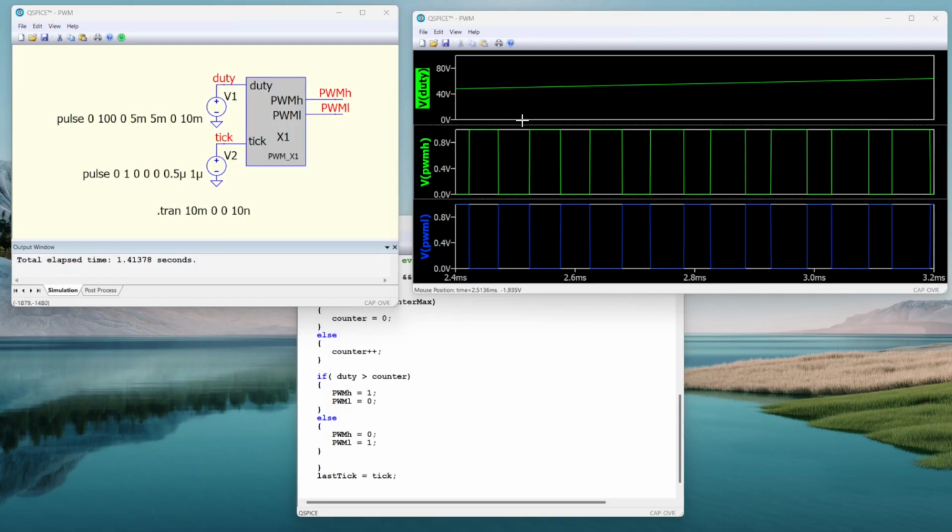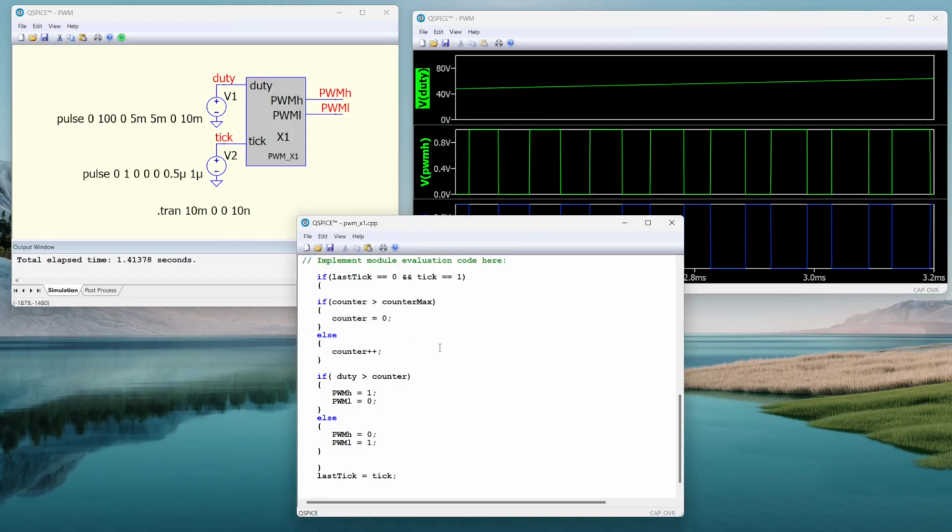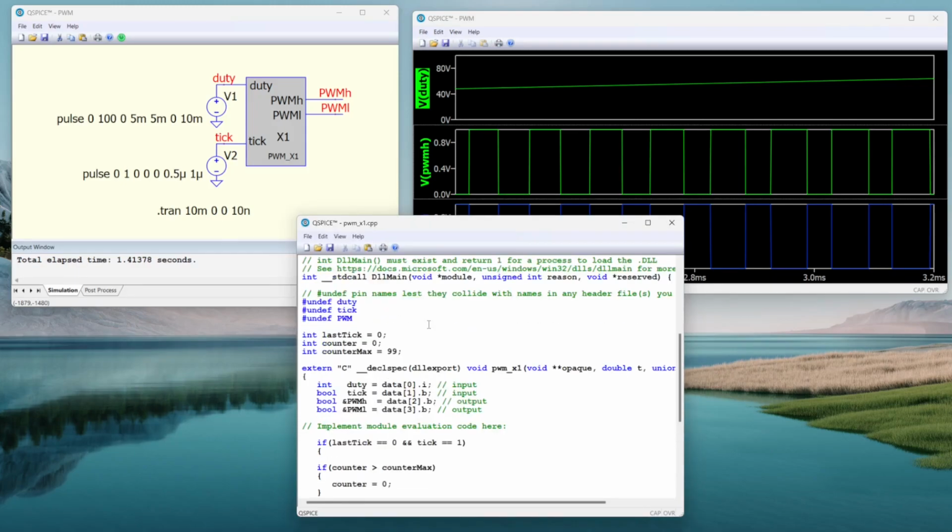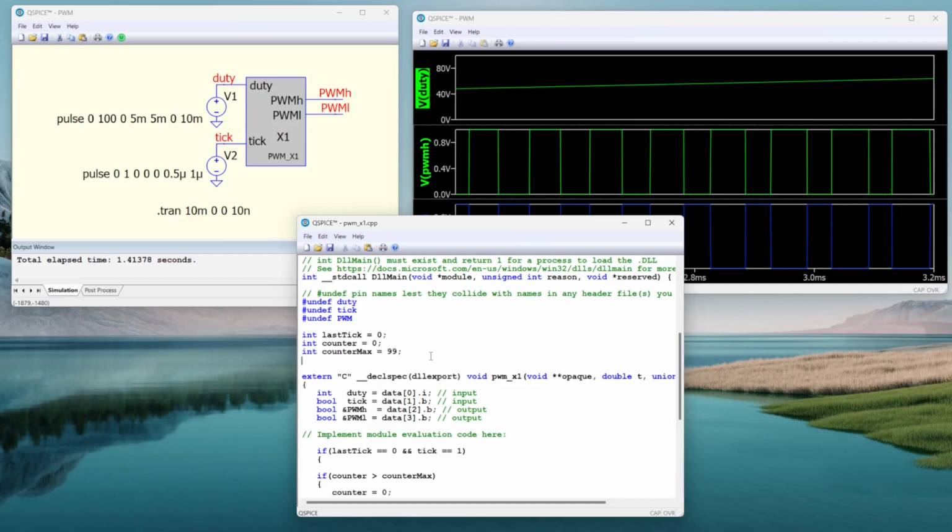For driving switching converters, this is still a problem, and therefore we need some dead time in the transition. And this is the next part I want to include in the code. The dead time is always in a microcontroller defined with ticks. So I will define how long the dead time should be.